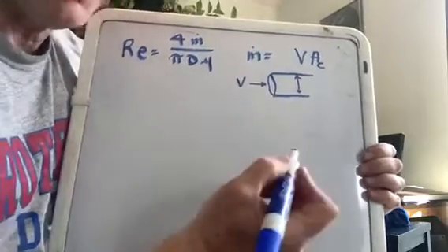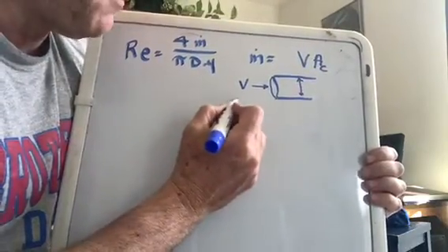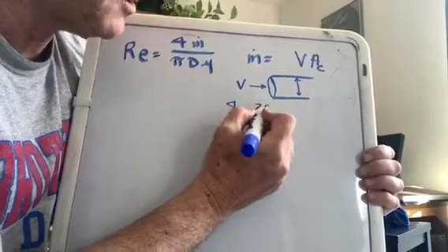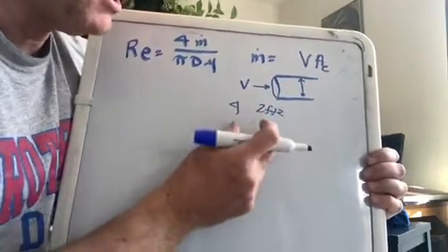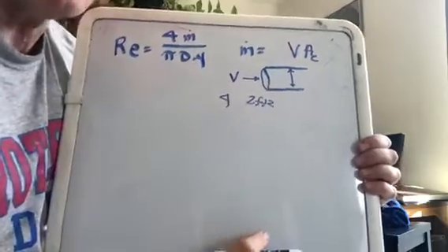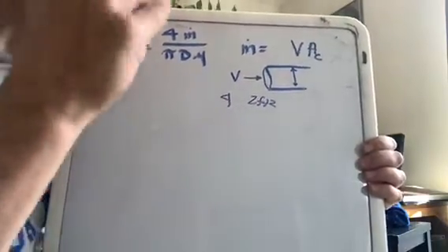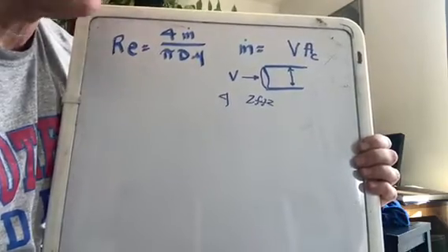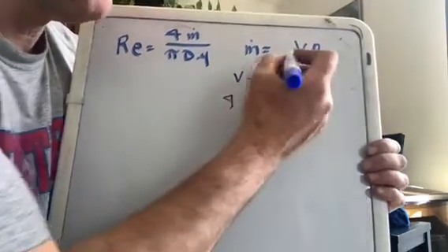I mean, just taking a numerical example that you don't need to write down. If a fluid's going 4 feet per second and it's going through an opening that is 2 feet squared, we're going to get a volume flow rate of 8 cubic feet per second going through that pipe. All right, how do we turn that 8 cubic feet per second into a mass flow rate? Well, we would multiply by the density.